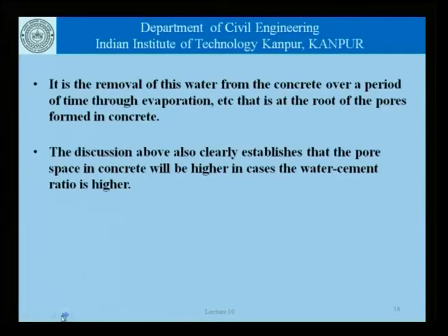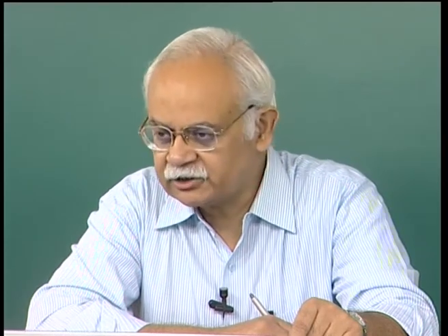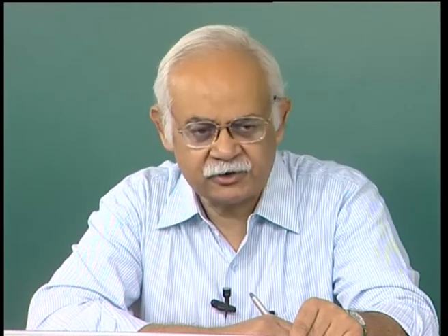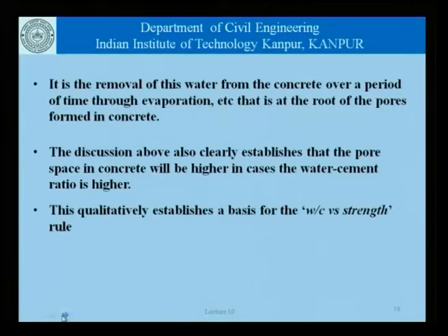This discussion that we have had about more water being added to provide workability, some of it remaining behind at the end of the hydration process, clearly establishes that the pore space in concrete will be higher in cases where the water cement ratio is higher. If we add more water, that is, we increase the water cement ratio, the amount of water that is left behind at the end of the hydration process will also be more, and that qualitatively establishes a basis for the water cement ratio versus strength relationship.